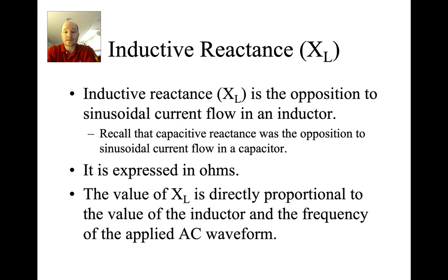The value of X of L is directly proportional to the size of the inductor and the frequency. What does that mean? X of L, inductive reactance, is going to get higher as the frequency increases or the size of the inductor gets larger. In lab, we're going to see how both of these operate. We'll do one where we change the size of the inductor, and then we will also see what happens when we have the same size inductor but increase the frequency.